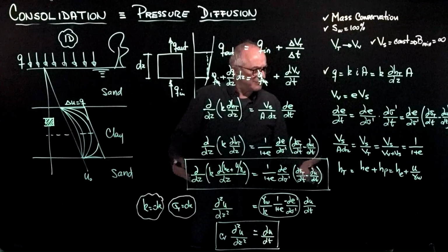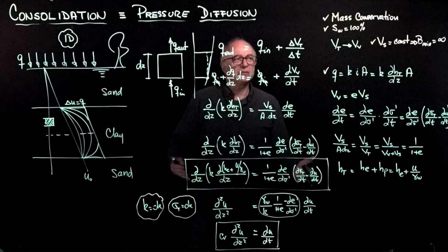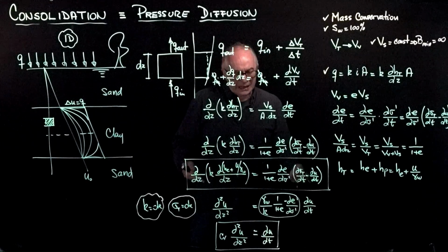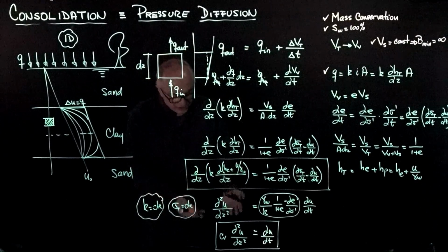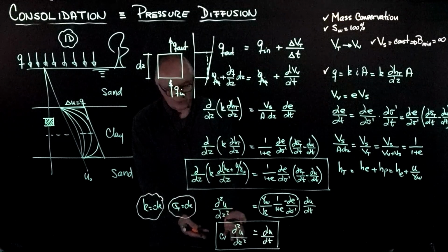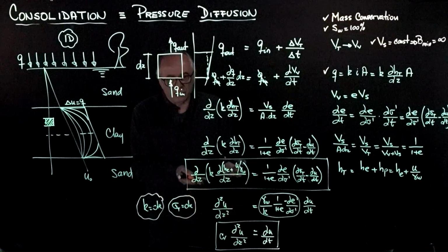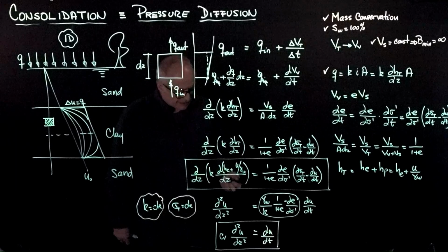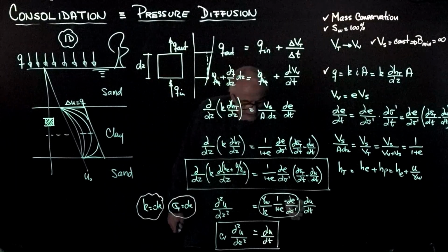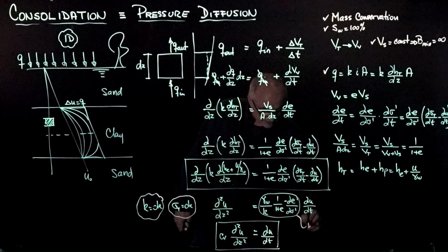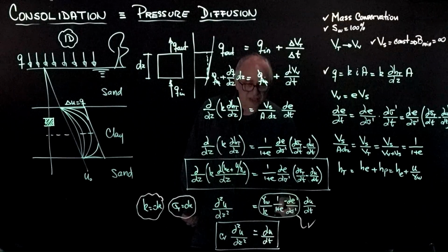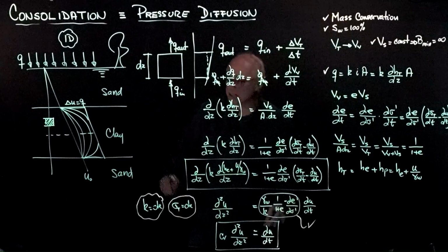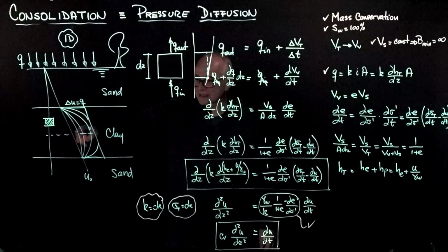There are a large number of assumptions that we are making all the way through, and if for some reason some of them do not apply, you cannot go automatically to the last equation. You have to come closer to the surface. In particular, we assume that this quantity here is a constant. But notice that the void ratio is changing because the effective stress is changing as the excess pore pressure escapes.